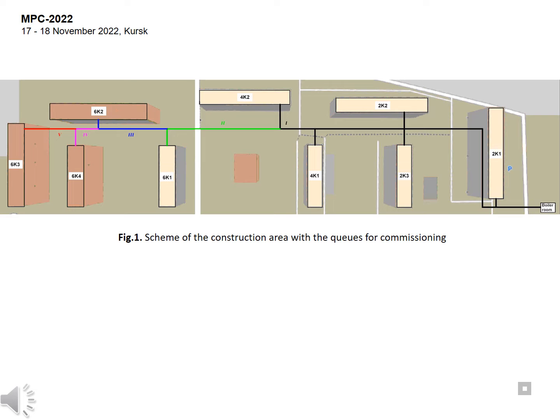Estimated water consumption for the heating network of the first stage of construction is 240.7 tons per hour. The total water consumption for subsequent stages of construction is 180.85 tons per hour. Thus, the consumption increases by 75.14%. It is necessary to connect all subsequent stages of construction to the heating networks of the existing configuration of the first stage of construction.